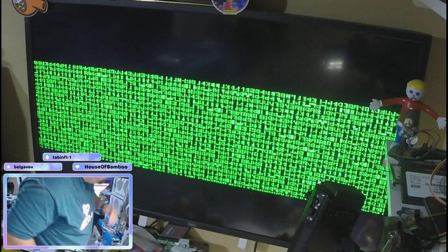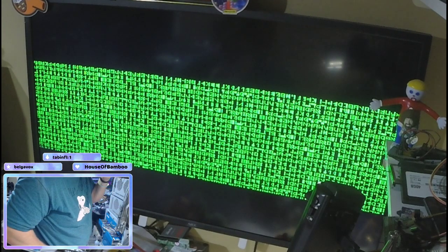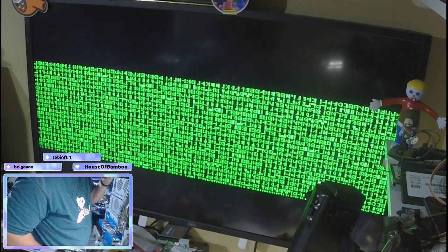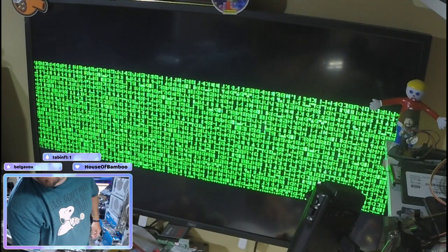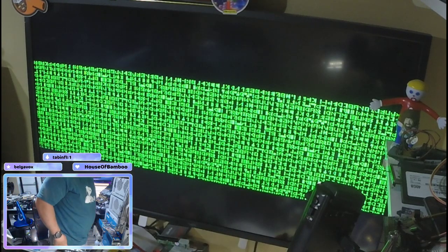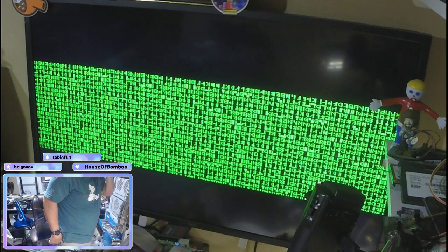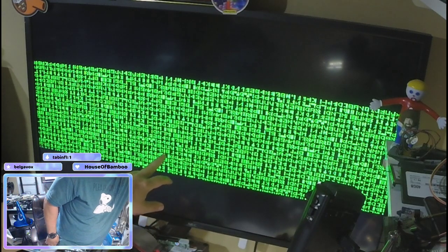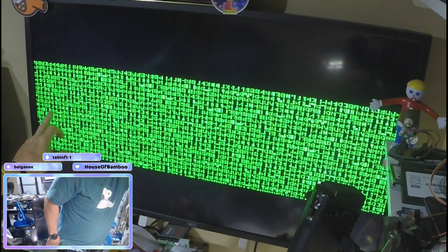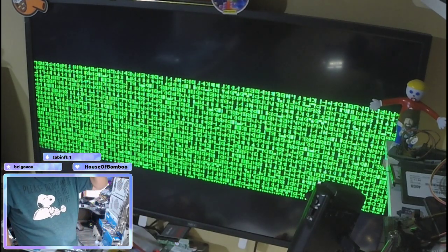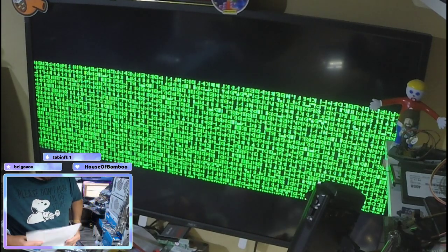No. I'm going to have to think about this one. I would say it's indicative with bad character RAM, because it's the same on every single character. Every single one of them has this bar in it. So the fact the screen is dumping stars on the reboot might be because I have no keyboard hooked up to it.